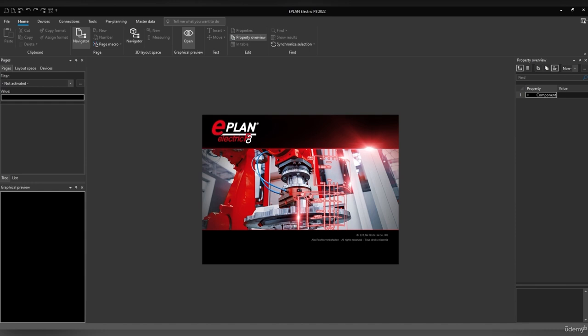EPLAN also has 7 project extension types. The first one is the .elk, the normal editable project. The second one is the .ell, a project with change tracking. Basically, when you change something in the project, it tracks when those changes were made. The third one is the .elp, a zipped project. The fourth one is the .els, a filed off project.